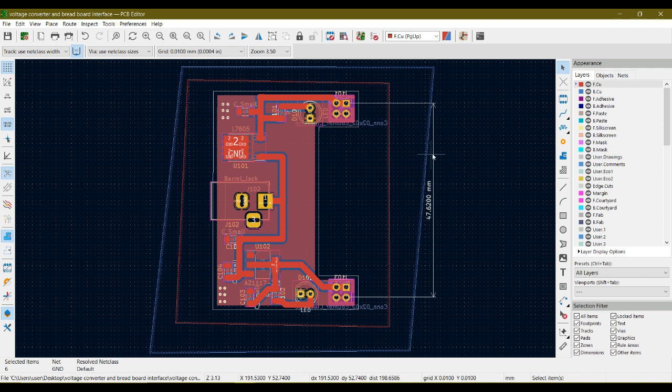So we have also finalized this, so let's delete these dimensions we have written over here. We no longer need this, and that's it. This is how PCBs are designed in KiCad. In the coming videos we will be using its silk screen, so that we must know which connector has 5 volt output, which has 3.3 volt output, and we can also add some logo over here. You can write your name over here. We will see in the next video how to do all these things.